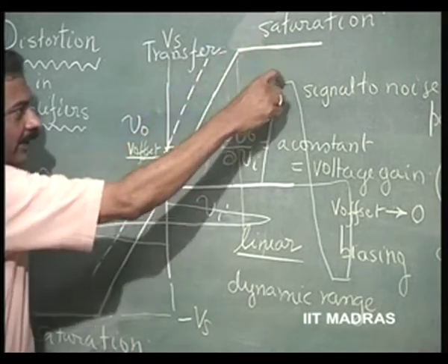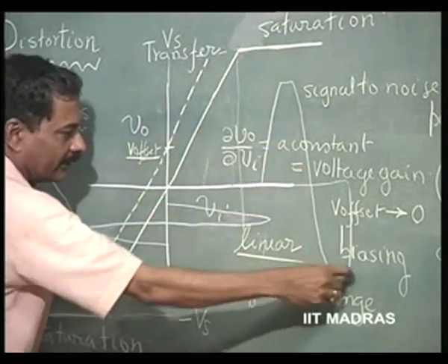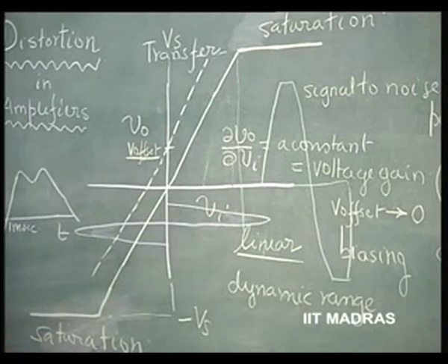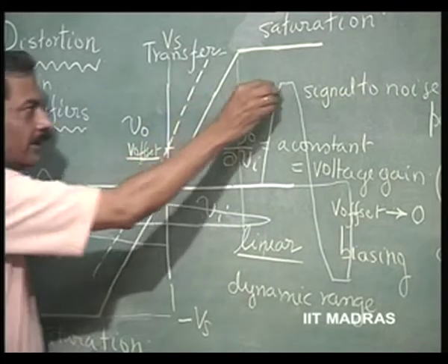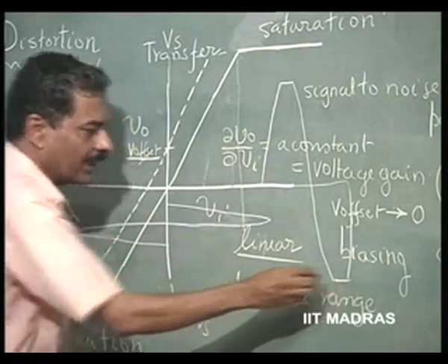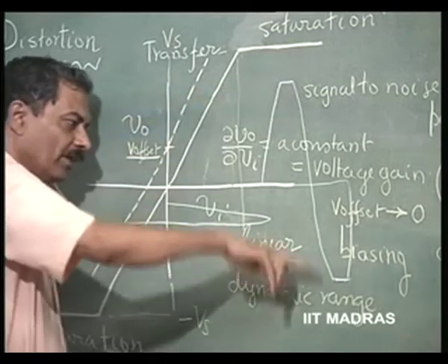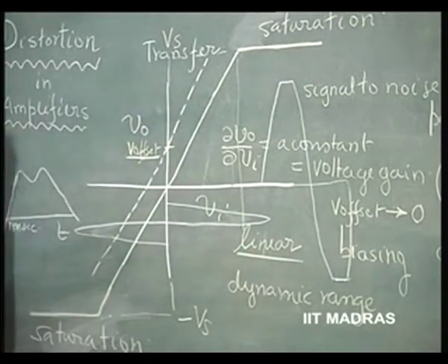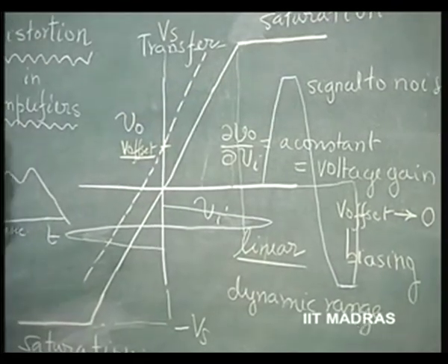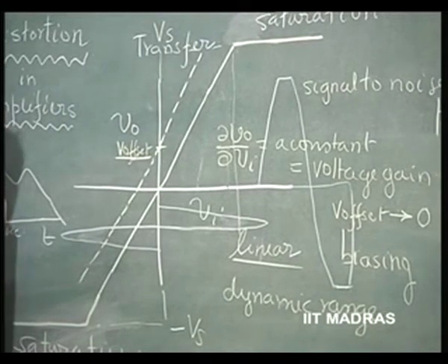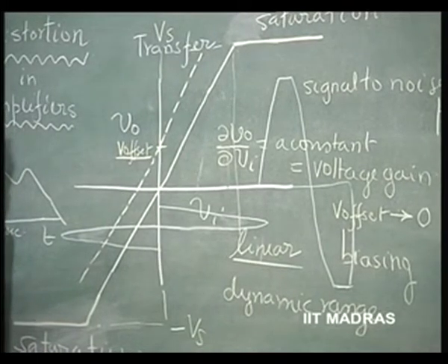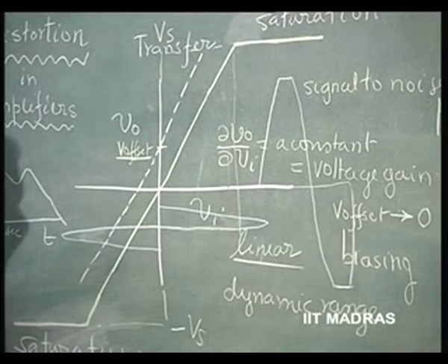Thereafter, it is going to remain constant. Again, so is the case with the lower limit. So, this kind of chopping off is due to saturation. This occurs in all amplifiers. Okay. So, if you see anything like chopping off the head of your sine waveform, okay, you can immediately conclude that you are applying a signal which is too large, and therefore, output is getting saturated.